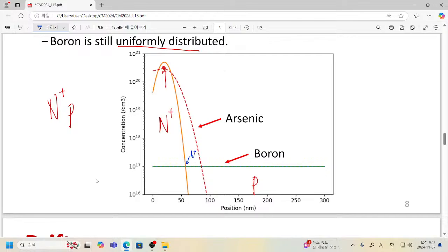You have a PN junction, and at the metallurgical junction, you inject a hole into it. Then it will feel a strong repulsive force from your N plus region, and it will be pushed back to your original p-type region.